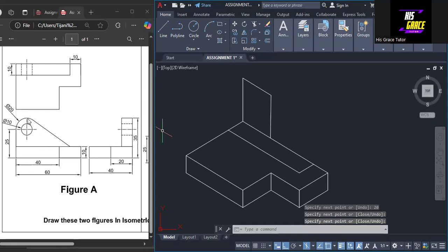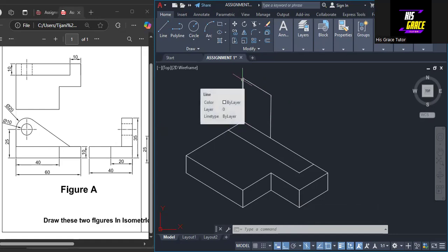So what you want to do is to create this curve here. And then we have the diameter is 20. So that's why we are going to create a square of length 20 millimeters. So don't forget that from here to here is 20. From here to here is 20. So that's what we have there. While from here to here is 25. So 25 plus this 10 of this thickness gives us 35 that we have from here to here. Okay, so that's what I did here.